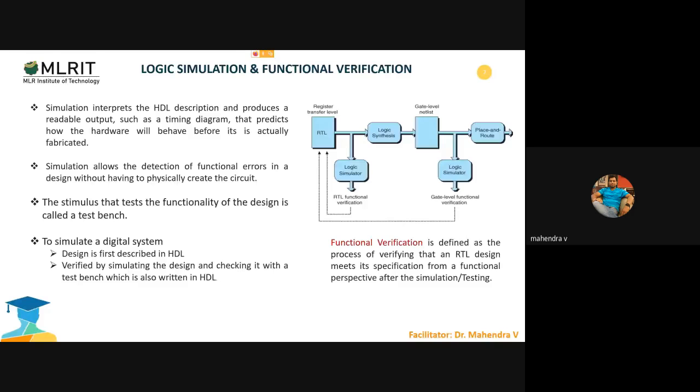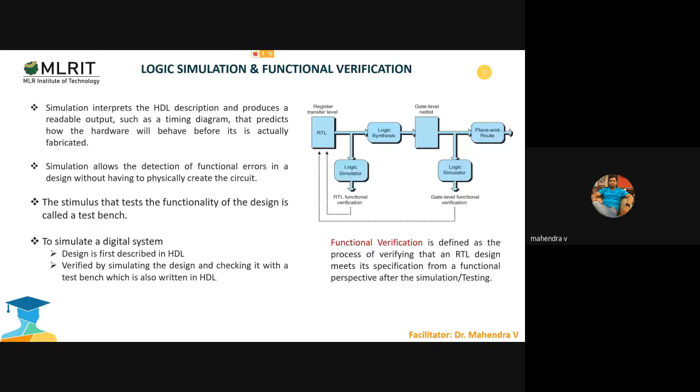And simulation means imitating the HDL code virtually. We can call that an interpreter. Interpreters always mimic the RTL code. Now the simulator produces the output based on the inputs we give, and functional verification verifies the outputs achieved after the simulation against the specifications we have captured.